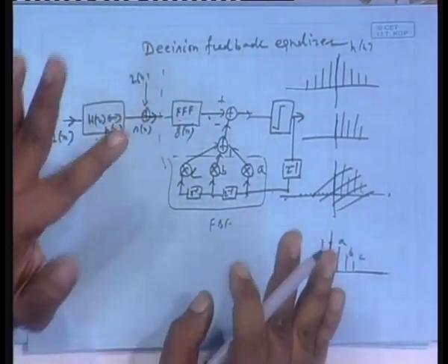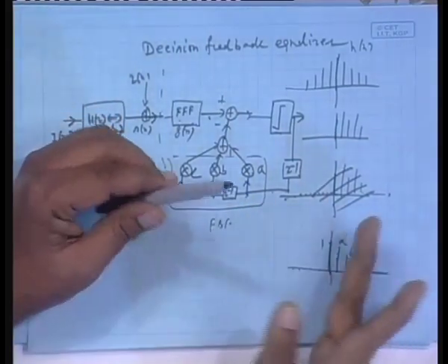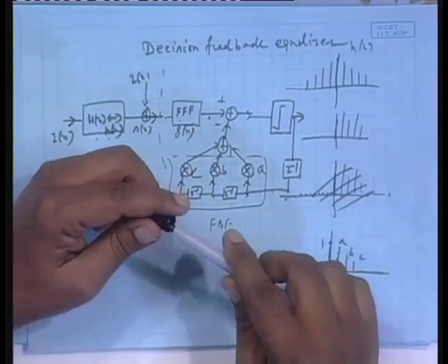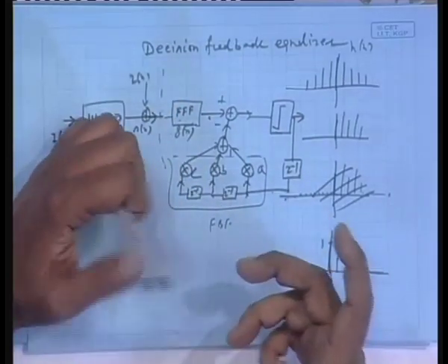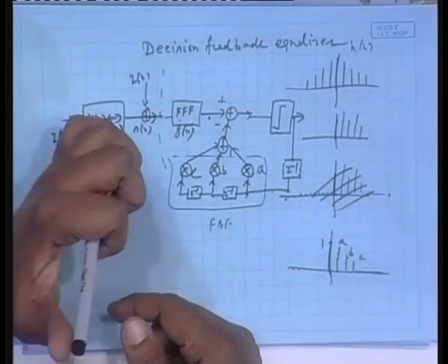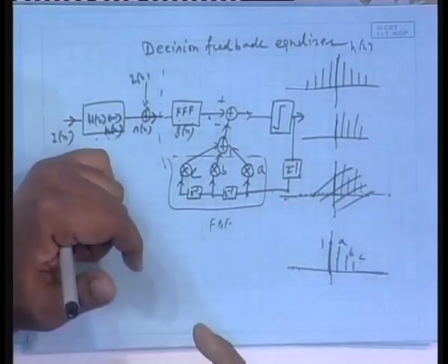So, this is another very important example for adaptive filter. There are plenty. Another example I forgot to mention today. Another example I gave that day was a smart antenna, beamformer. That is, in the same cell, I can give the same frequency to two users located in two different directions, but by adjusting the antenna gains, I can form a beam in one direction and a null in another direction. So that even though two users are using the same band, I can hear only one, the other person cannot interfere, and if this person is in motion, my beam should lock on to them. So, it has to be adaptive. That is called adaptive beamforming. In the last class, I gave that example too.